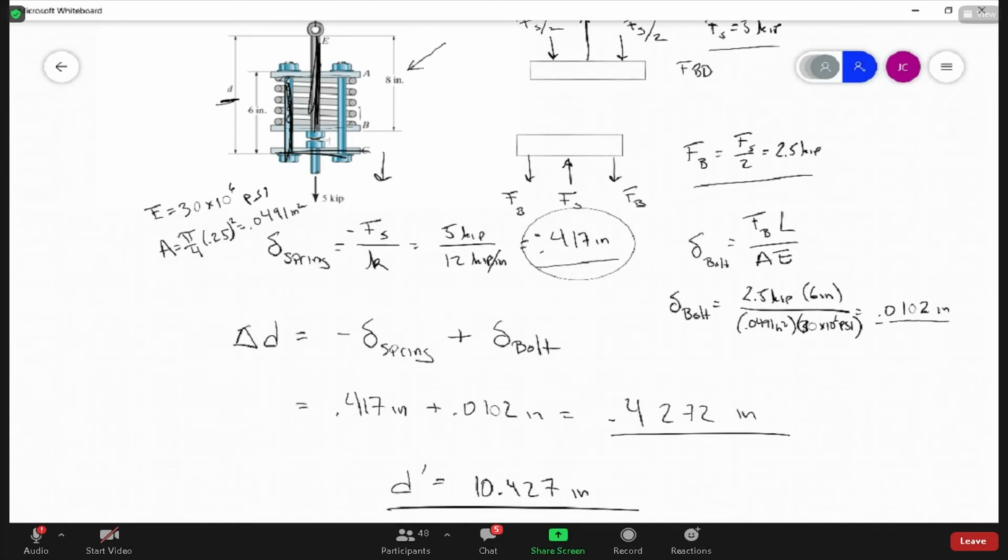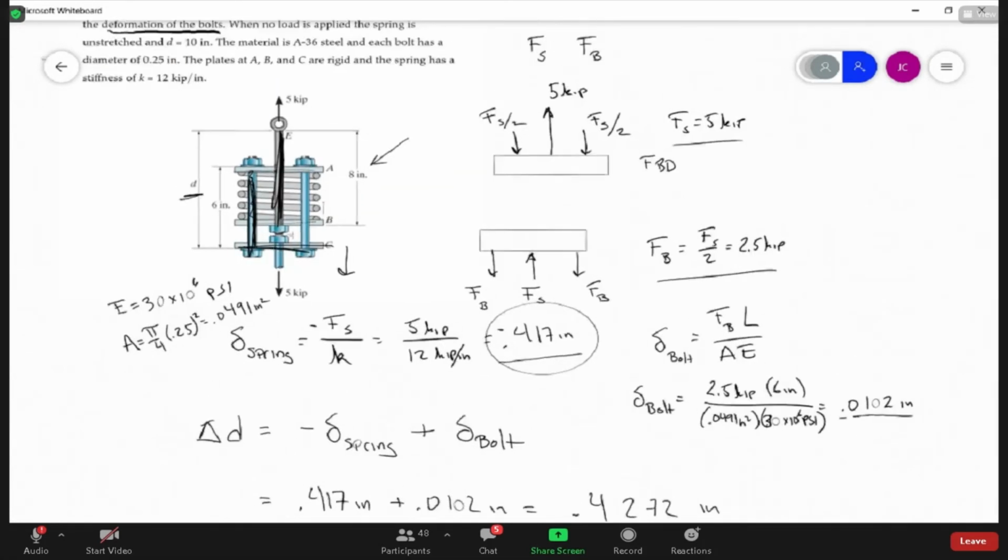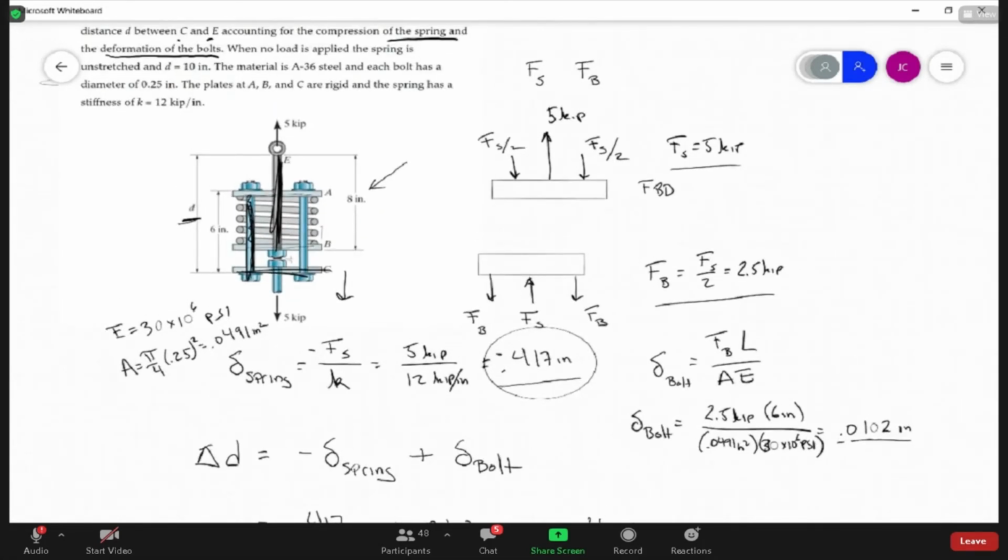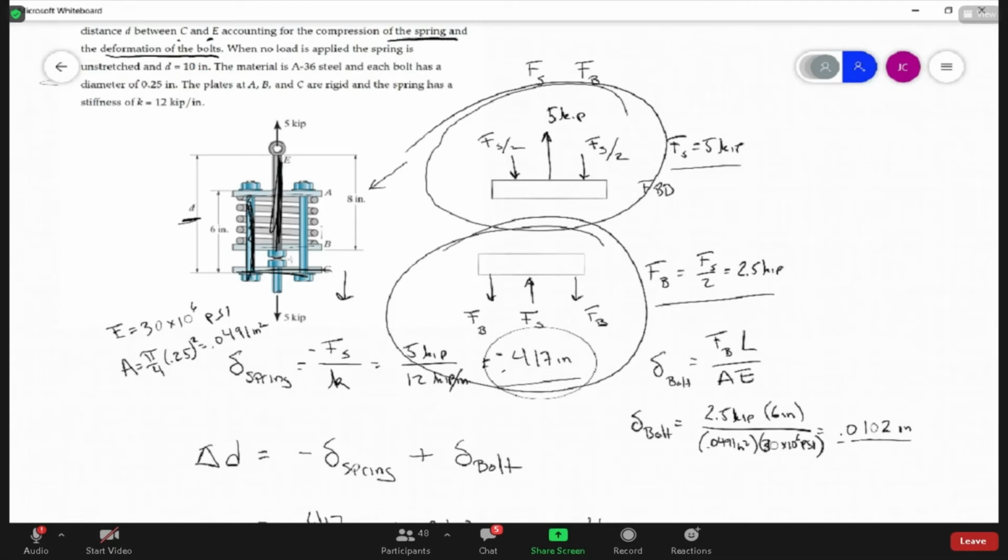All right. Two things though. Again, good problem. What are the forces in the spring? What are the forces in the bolt? Don't let all these questions confuse you as to how to start the problem. You have the tools that allow you to dissect it. Free body diagrams easily show you how the external force is related to the force in the springs and the force in the bolts, and it's not confounded by how much they elongate.